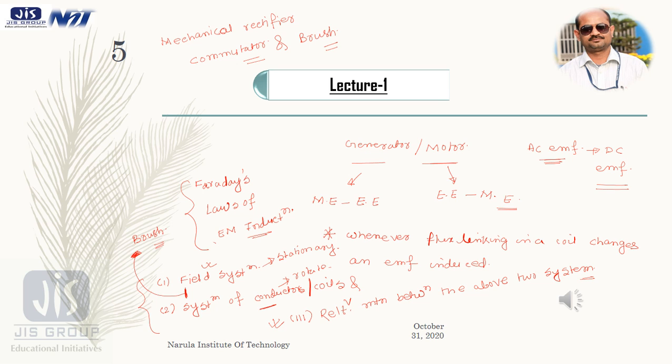Okay, and where to place these brushes? We can place them in the rotating system or in the stationary system, but it is not practical to place them in the rotating system. So for ease of operation, they are placed in the stationary part of the machine.